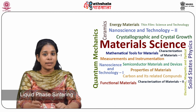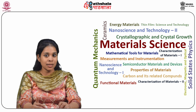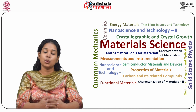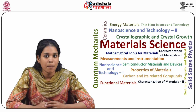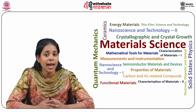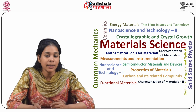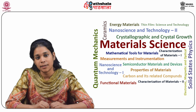So liquid phase sintering is the second sintering which we have read, and in this some liquid is present during some part of the sintering cycle, and the initial densification occurs due to particle rearrangement due to capillary forces. Further densification occurs by solution reprecipitation, in which the sharp corners and edges of the solid particles are dissolved by the liquid and transported through the liquid and deposited elsewhere, leading to a rounding off of the grains.